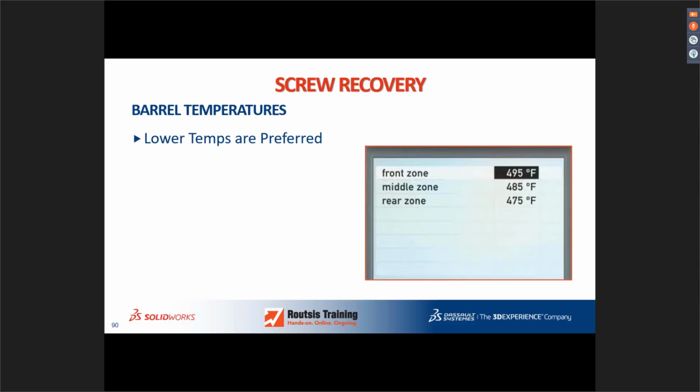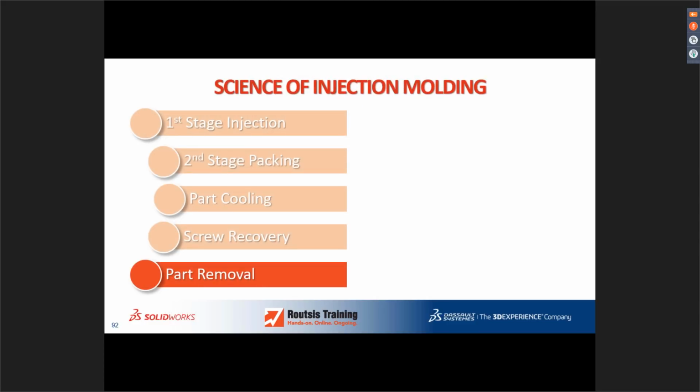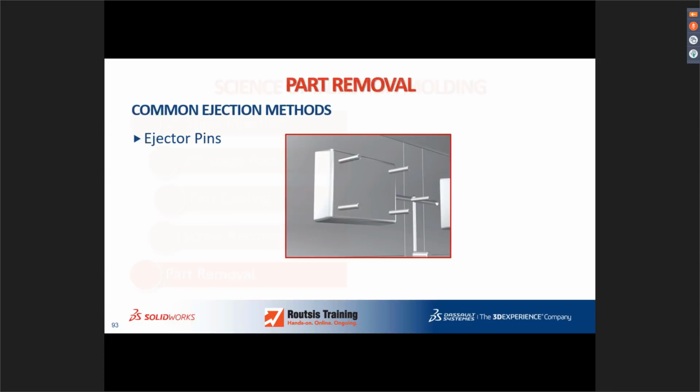Screw recovery is important. We want to have a consistent temperature whenever we mold. And it's a good idea to simulate and recommend a melt temperature when you're doing your simulation. And lastly is part removal.